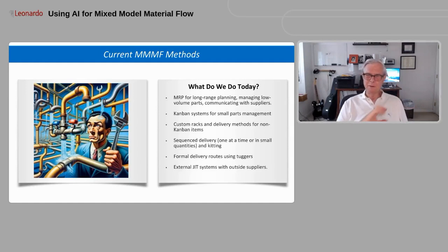It was a button that you put on it that said no MRP, and it had a not sign. But people misunderstood that. That didn't mean you don't have an MRP system. It means you don't use MRP for shop floor control, is what that meant. That we have a visual pull system on the factory floor, not scheduled through MRP. But when it comes to materials, you really do need MRP.